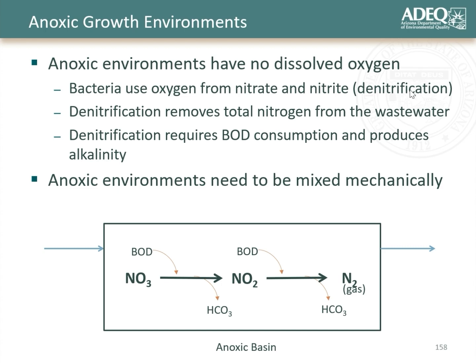An important factor to think about is that there is no aeration happening in the anoxic zone, because we do not want to introduce oxygen, because otherwise the bacteria that do denitrification would just use oxygen instead of the nitrate. To keep these organisms in suspension, though, we have to use mixers that keep them mechanically mixed so they're staying suspended. Otherwise, without aeration, without mixing, they would just settle to the bottom. So it's an important factor associated with these environments.